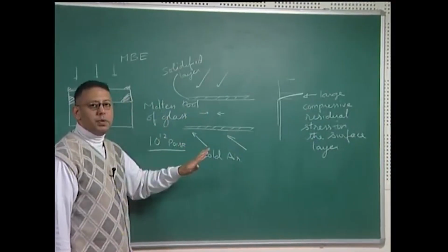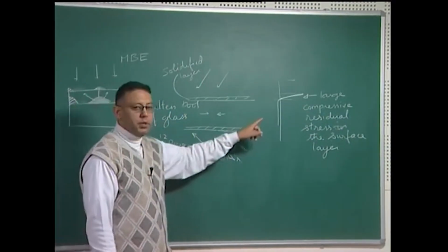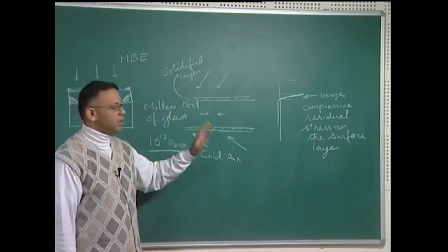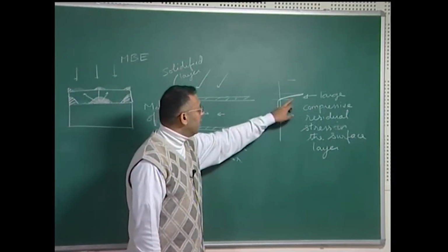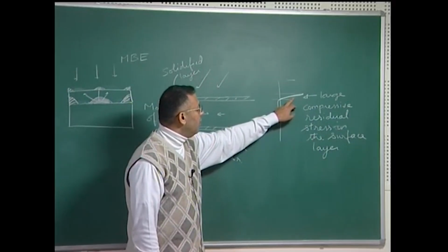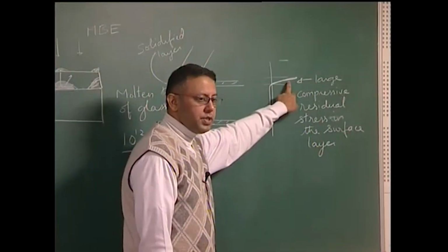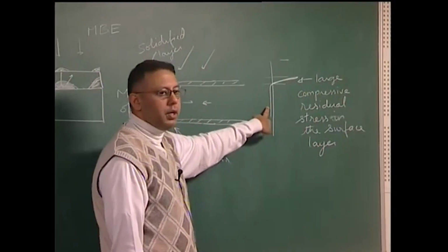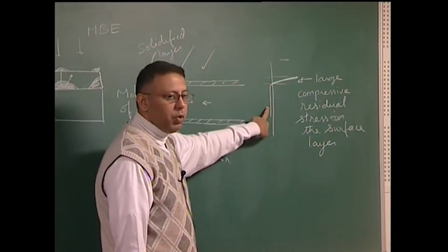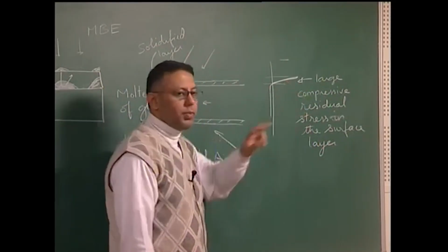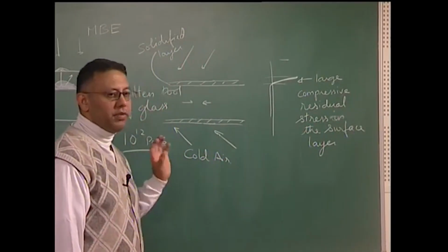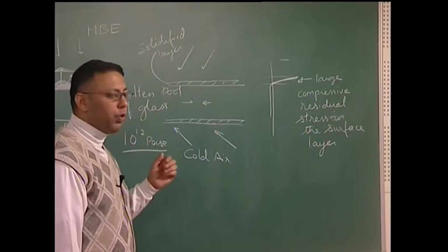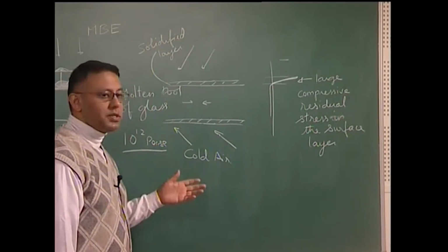What we have barely played around with is the presence of residual stresses, and as we know, residual stresses are always 0 overall in the body, given by the formula integral of sigma dV equal to 0. Therefore, the outer is in compressive stress, there is a small residual internal tensile stress in the middle of the body, but this large compressive residual stress gives rise to a large strengthening or toughening of the glass, which can be 3 to 4 times or even higher in many cases.